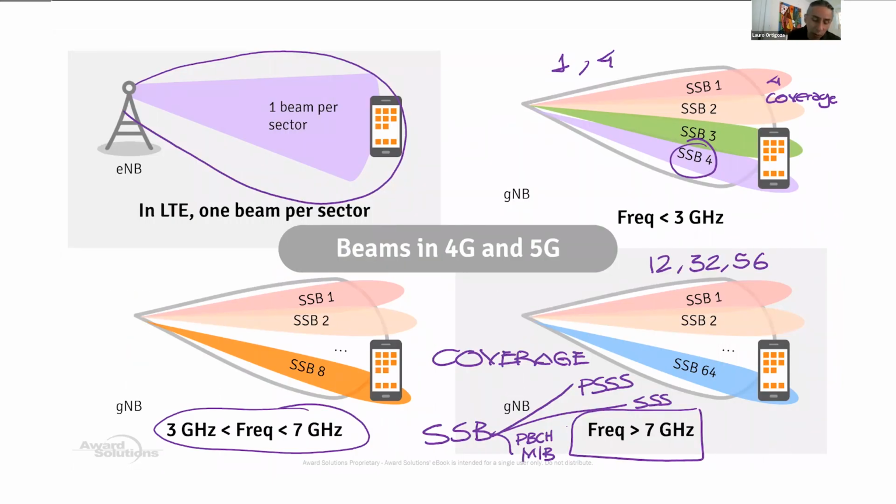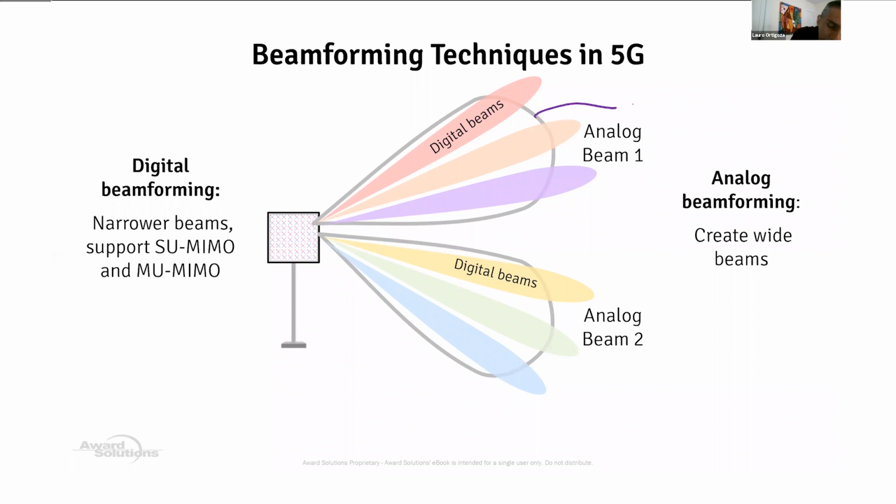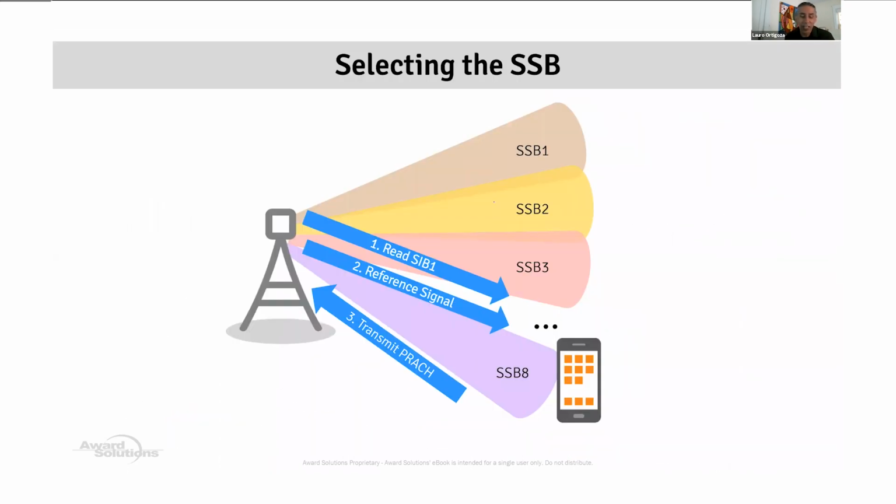And as you see, in this example, I'm showing you 4, 8, 16 beams in the time domain. So this beam 0 goes there, beam 1 goes in here, 2, 3, 4, 5, 6, 7, 8, and then vertical. Those are called my coverage beams, and they transmit. They use 20 resource blocks, right? 20 resource blocks. And typically your vendors put these SSB beams or coverage beams in the middle of your carrier, okay?